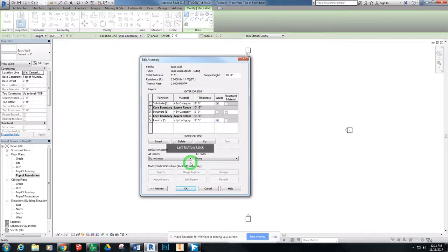So I'm going to change this to 1/2 inch. And modifying, I'm going to make this 4 inches. This is going to be our 2x4 wall. Now, nominal lumber is actually 3.5 now, but at the time that Walden's cabin was created, a 2x4 was most likely close to 4, although it had a lot of variance. It wasn't exact as manufacturing is now. And on the outside edge, I'm going to go 1 space 1/2. We use 1.5 inch thick lumber for our siding.